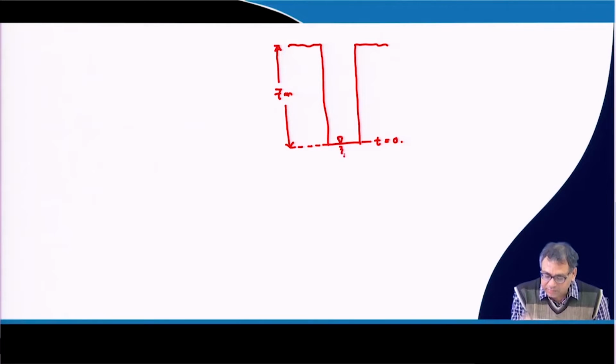meter from the ground surface, and then with time the distance of the water table from the ground surface is measured, and the rise of the water table within the borehole is measured. So, this is say at t 1 equal to 24 hours, this is the position.